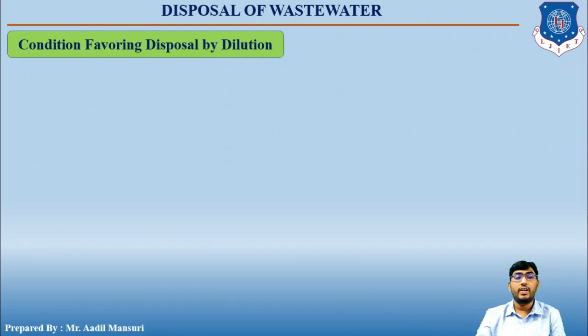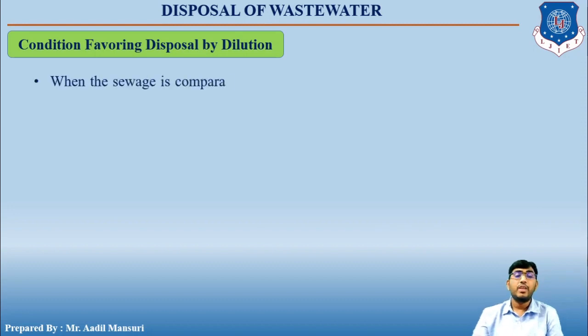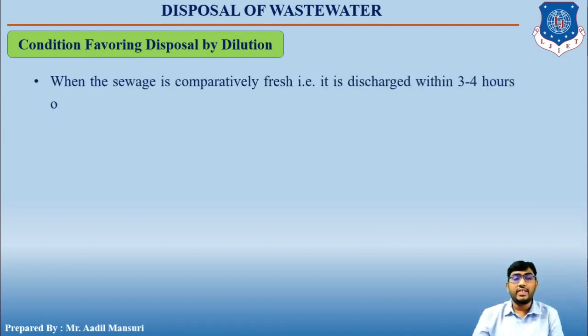So let us move ahead. So let's talk about the conditions favoring disposal by dilution. When the sewage is comparatively fresh, that is, it is discharged within 3 to 4 hours of its collection, then you can go for disposal by dilution.